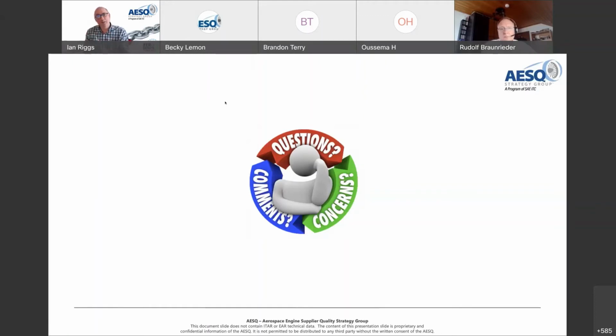So there's still an awful lot you can do on a process FMEA without the design, right? Because you should be experts in what it is you're producing. You will have knowledge of what happens when certain things go wrong because it would have happened before and your customer would have talked to you and you'd have known that this thing caused an in-flight shutdown, or that this thing has a performance issue to the engine.